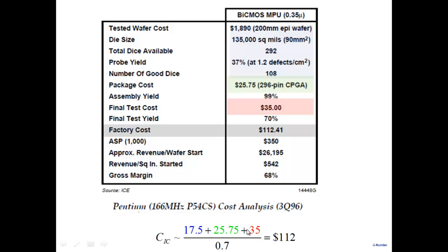Microprocessor is a complex entity. Memory, on the other hand, is much simpler. Microprocessor is complex and testing cost is very high. Now, if you cut down on testing, well, then there's a price that you have to pay. Now, testing is something, think about what you are doing in testing. Our 8-bit adder, how would you test your 8-bit adder? You've fabricated, done everything, right? How would you test your 8-bit adder? Well, you will apply one 8-bit input, the other 8-bit input, and see whether the output is correct or not.